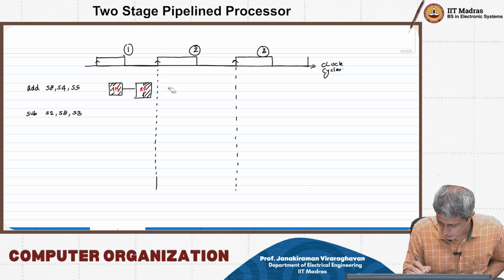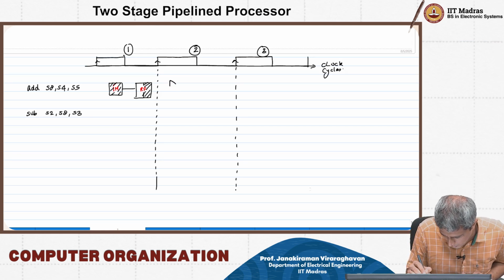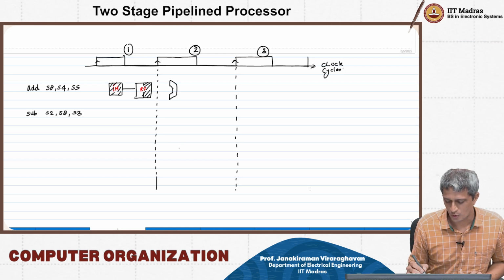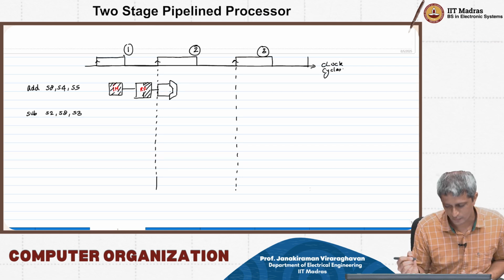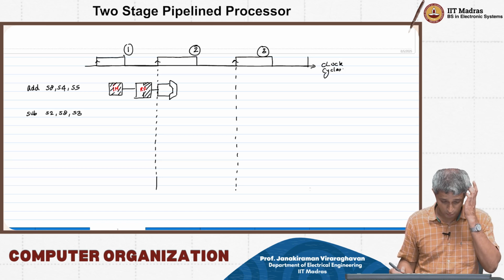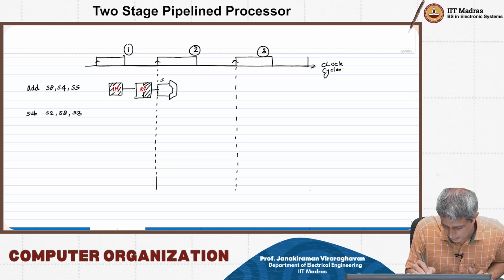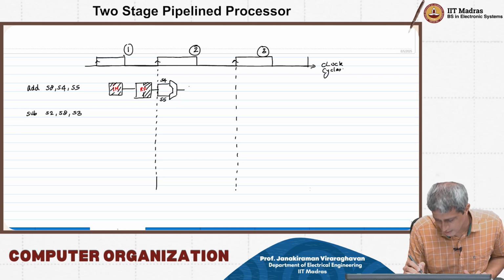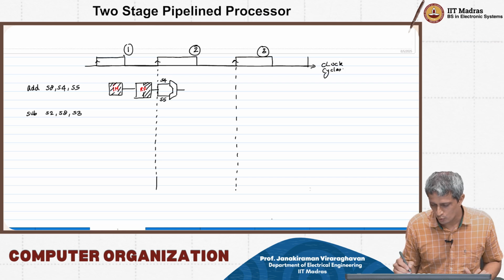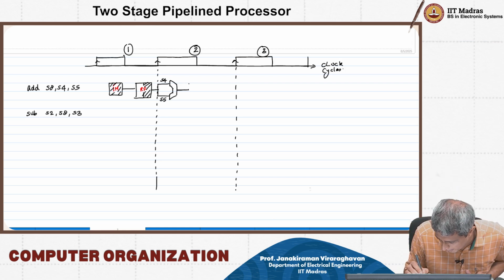So here is where the ALU will kick in, okay, and the register file is going to give you data, okay. That is going to, basically the source registers are S4 and S5, and this is then going to go through the ALU. Then it is going to bypass the data memory because there is no data memory operation happening.